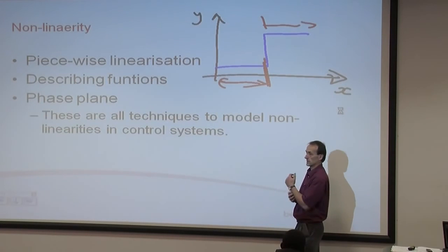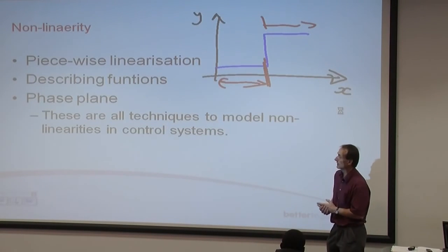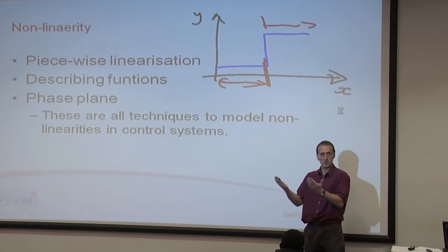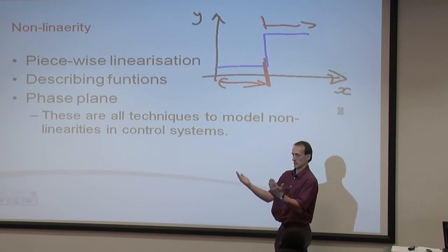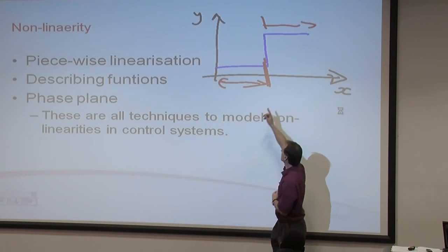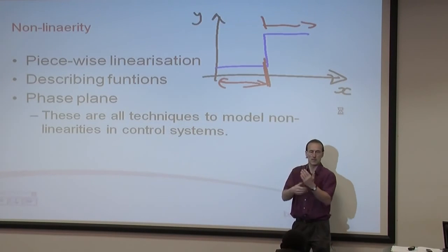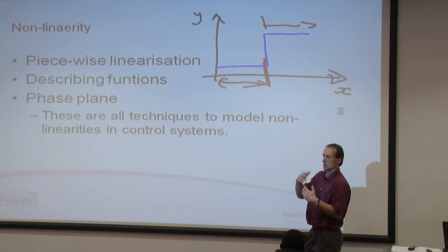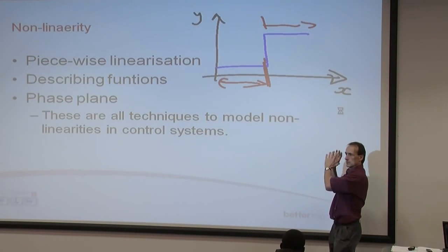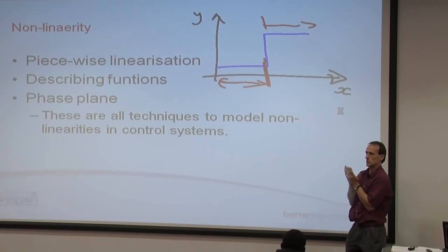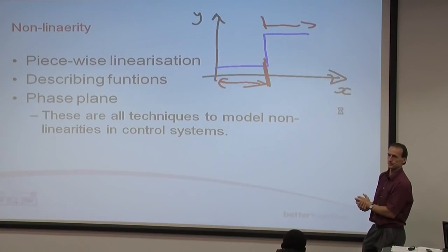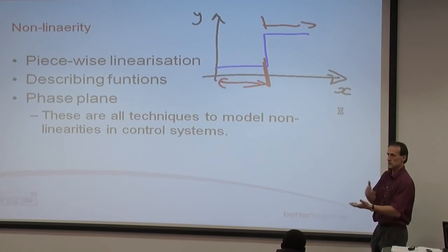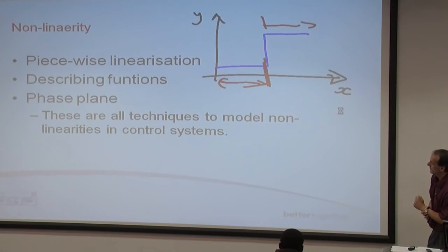You'd produce kind of vector diagrams of what the system's doing, and depending on how you arrange your controller, well, putting it crudely, you take the two different pictures and you cut them up the middle, and that middle represents the switching point, and you join them together, and you can then produce a describing function which shows you the behavior of both halves of that system joined together with this switching device in the middle. Okay, that one's quite good fun because you can physically do it with a pair of scissors and sellotape, so it's quite visually easy to see what's going on.